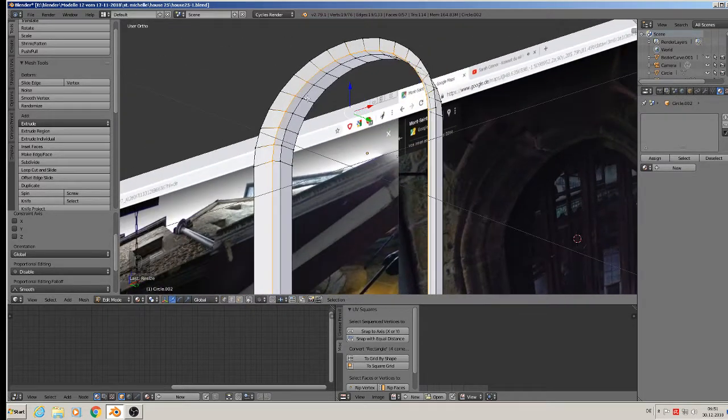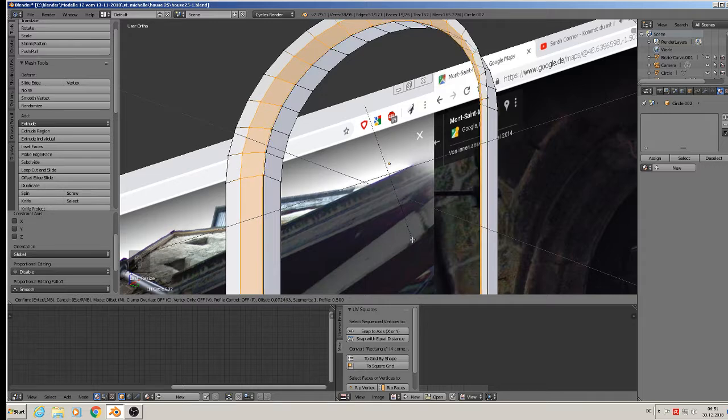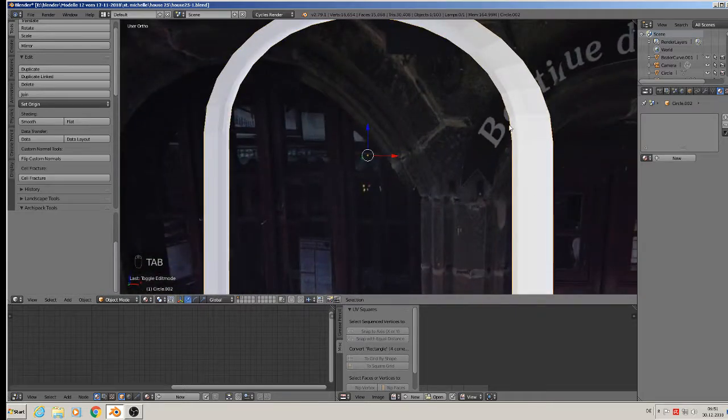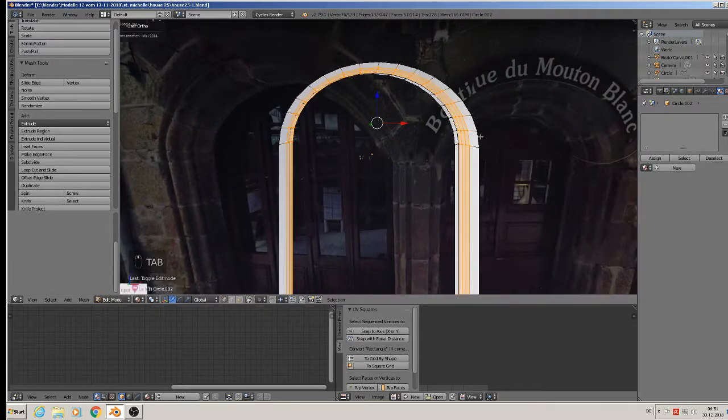And with them we now want to make the roundness. So we take Control B to bevel mode, we get the influence area and roll the mouse. So we see we now have that round part with smooth. It looks perfectly round. Then we take the next part, so extrude again.